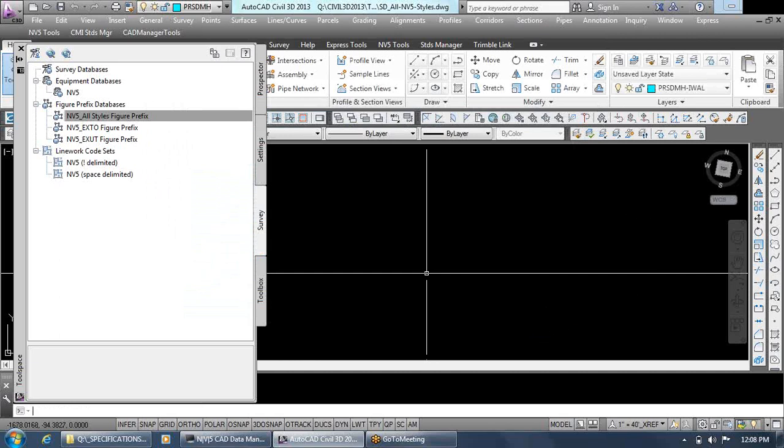All right, a couple issues that I've been made aware of. The first being the undo command. I know quite a few of you have had issues with the undo command, be it not working, not actually undoing anything. There's a couple things that could be causing that. The first being hatches. Be sure that when you create your hatch that it's not annotative.